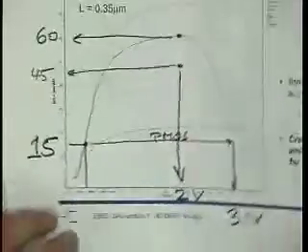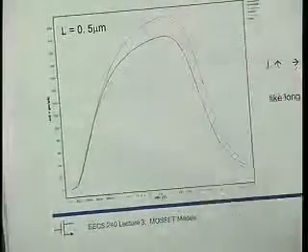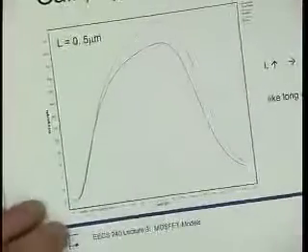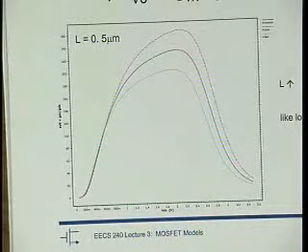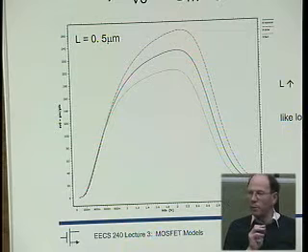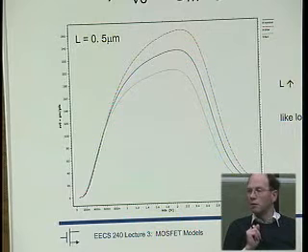Right? One thing that does help a lot is if we increase the channel length, right? Mucking around with this gm over ID will change it a little bit, but changing the channel length has an even more significant impact. One thing that you will often see is, whatever the minimum channel length of the transistor is in the technology that you're using, let's say 0.13 micron, if you increase the channel length by just a tad bit to, let's say, 0.2 micron or 0.18 or so, the rout, or the achievable gain of the transistor, increases dramatically.